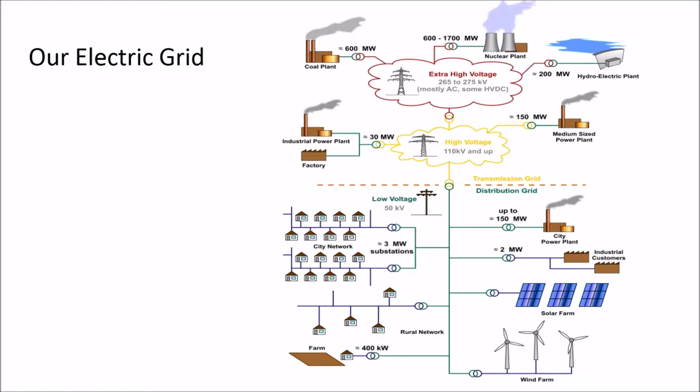So just some low-hanging fruit ideas that we've thought about when designing an off-grid home is to put the deep freeze on a timer so that the deep freeze only runs during the day. It has enough mass inside that deep freeze to keep the food frozen overnight if you're not opening it up. And so you freeze during the day and you let it coast at night. Alternately, there are all these new smart thermostats and radio-activated power outlets. None of it's really come together in a good, cost-effective commercial product yet,